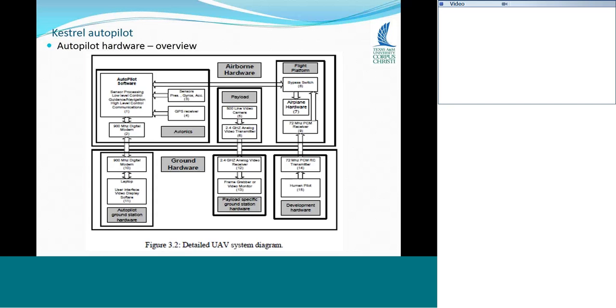If you're supposed to be flying on autopilot and everything's okay, then the bypass switch will say, all right, inputs from the autopilot will go to the hardware, the elevator, rudder, and so forth. If there's a problem, if I get a particular signal that says there's a problem and I need to give control to the guy on the ground with the joysticks, then the bypass switch will say, all right, the input from the ground controller will go to the hardware. All right, so that's how it goes between autopilot and manual. We'll talk about specifically the input that allows it to do that.